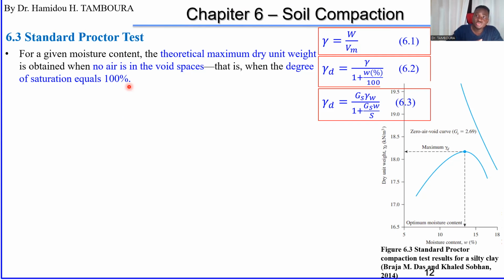Supposing that you succeed in reducing all the voids in the soil that are not occupied by the water, then your compaction will be perfect. It means no void at all in the soil. All the voids are occupied by the water, and for the voids not occupied by the water, you have compacted the soil to close those voids also.